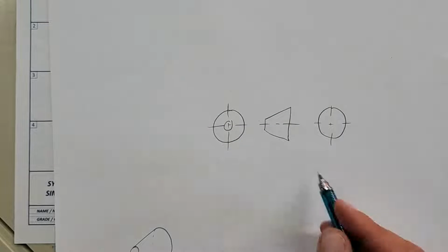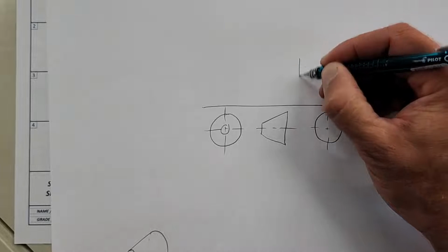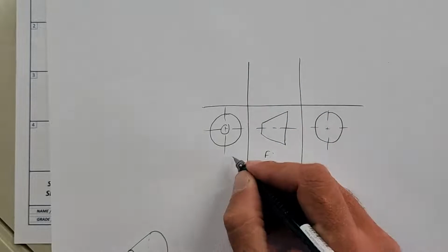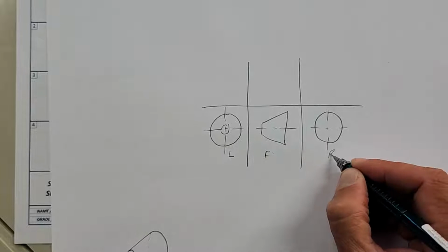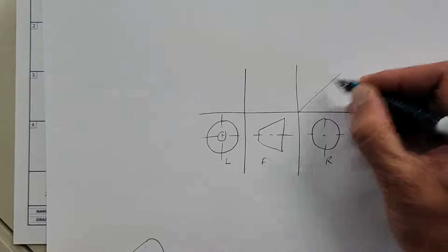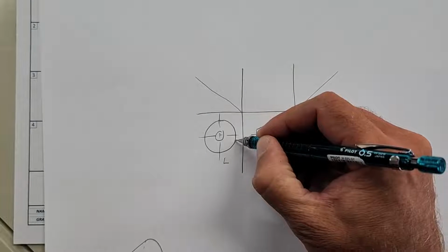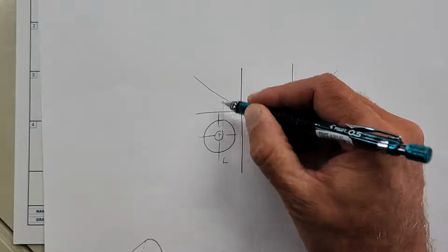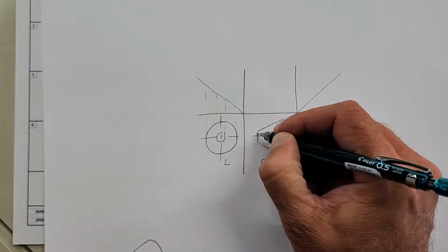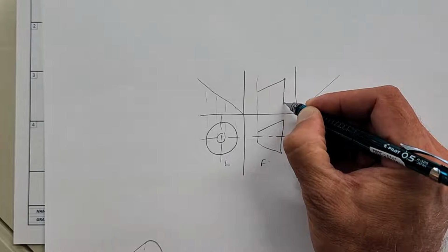All right. Now look here. If I put my XY axis in, that's the front. I'll just do F. That's the left, that's the right, né? Voor, links, regs. Whichever way I put my 45, if I project this up and across, and I project this up and this up, what I'm going to find here is a top view.